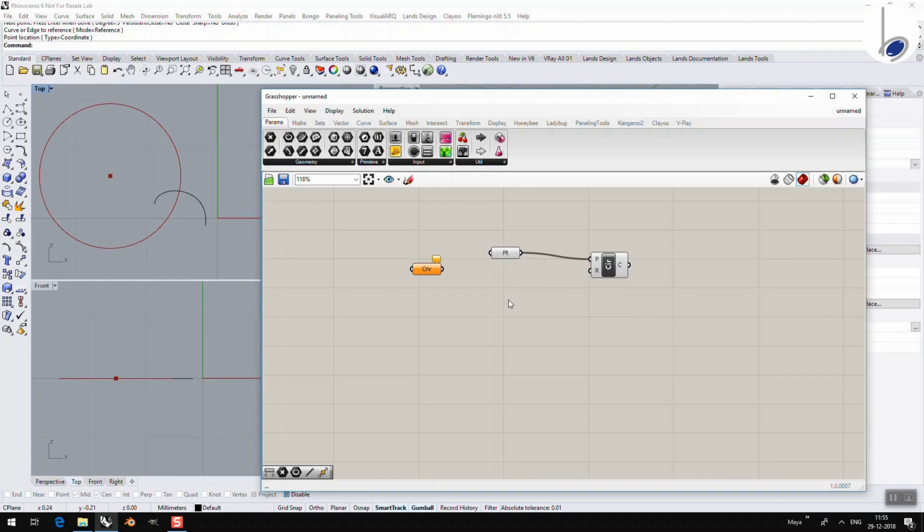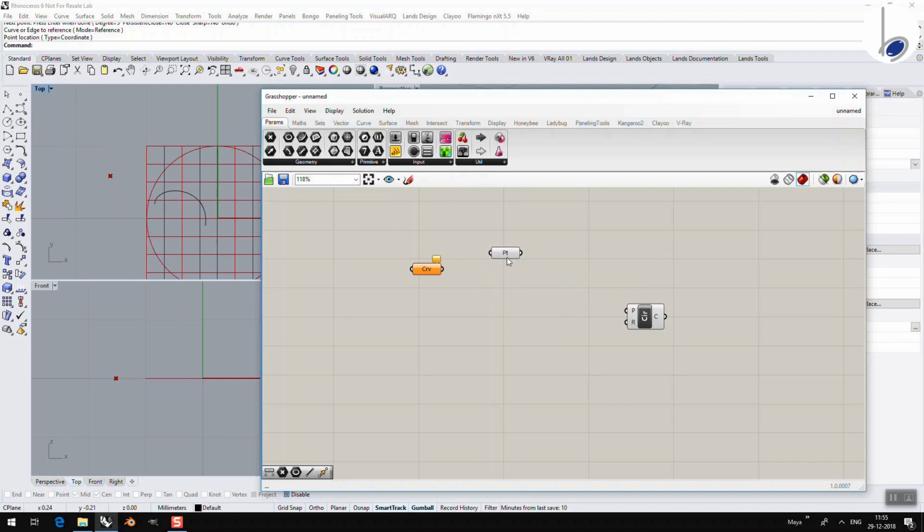Let us now look at what are color codings. I have different kinds of colors that are available as color coding in Grasshopper. The first one, as you can see over here, is an orange colored item. Orange color denotes that it does not have any information yet. As you can read, it is saying empty curve parameter. Because the information is not available, the parameter cannot pass information ahead, and hence it is showing orange color. This point, on the other hand, has some information which we had given, which is why it is in light grey color. This light grey color denotes a stable object. So it could be a component or it could be a param.